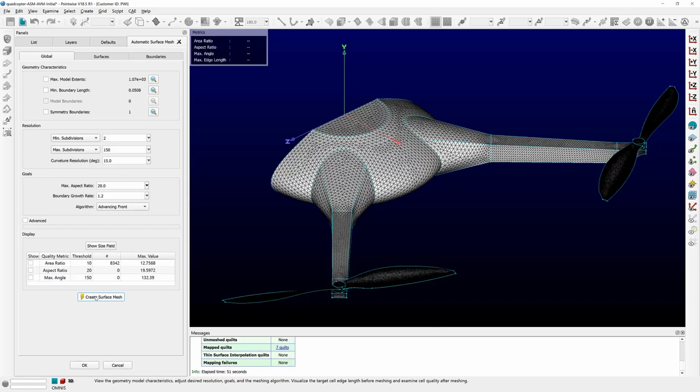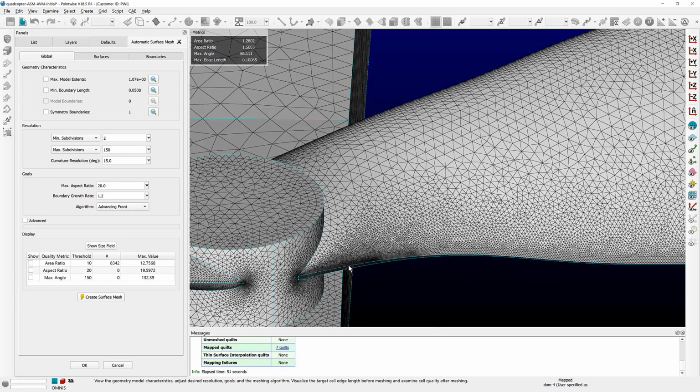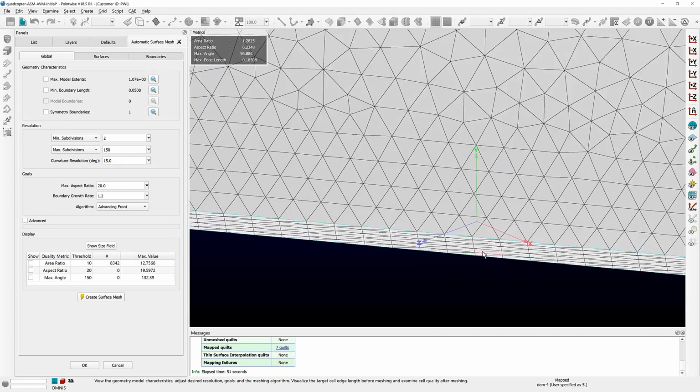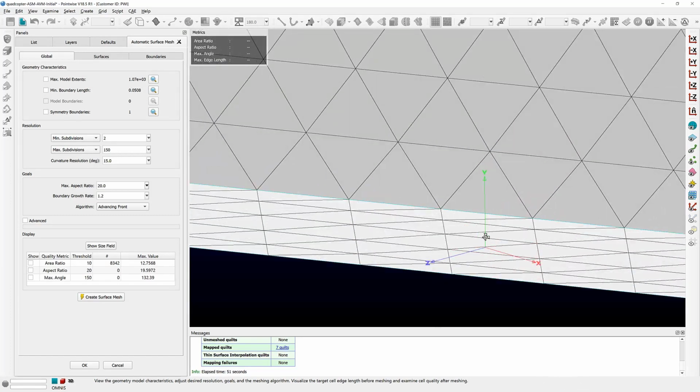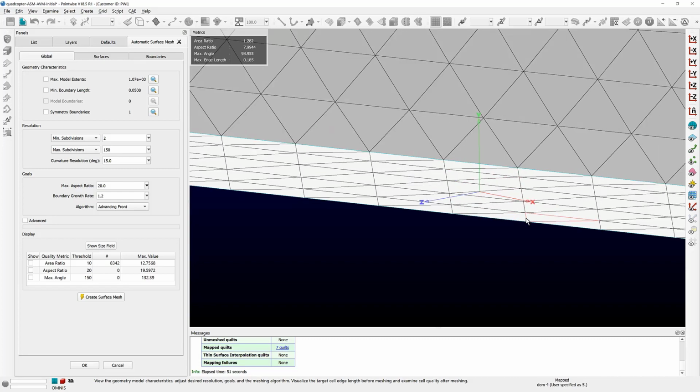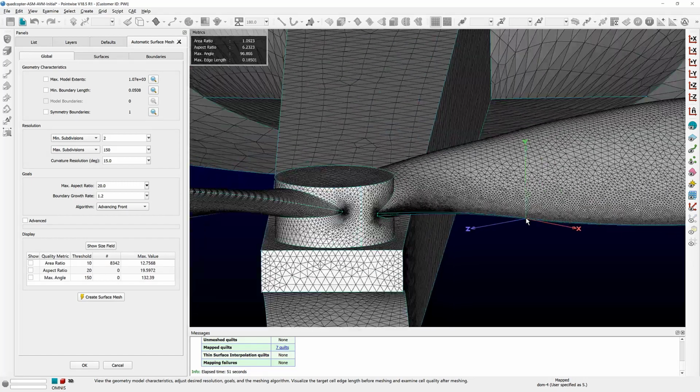Okay, our surface grid has been created based on the specification of the different parameters and all our settings. So let's see what we got. I'm going to zoom a little bit closer to areas of interest, like for example right here. You can see right there that we did have that enforcement of the number of cells that we wanted across the trailing edge. In our case, we have 6 grid points and we have 5 subdivisions. So that is actually very good.